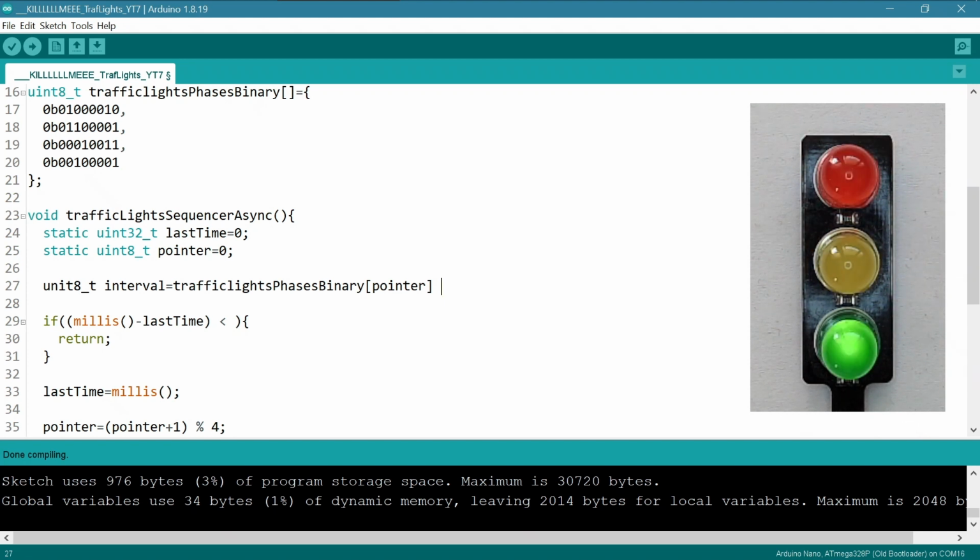So we have to do a bit of ANDing here. ANDing, I mean a logical AND. And since we're in Arduino, I can do the byte thing again. 0B1111. This is the part we don't want to keep. And 1111, this is the part we want to keep. Yeah, of course, I could say 15, or I could say it in hex. That's all the same. But I like the binary representation over here, so I want to go for that one.